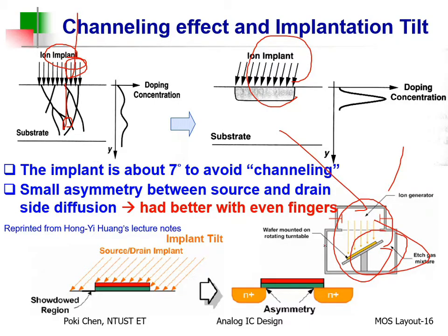But in this way, I told you already, the source, this area and that area, if it goes in this direction, the side diffusion here will be much larger than there. It means what? Your source and drain will never be exactly the same. They are not symmetrical at all. Got it? But for your simulation, it is supposed that source and drain are symmetrical. Right? So how to solve such kind of difference between the layout and your post or presim? You need to do such kind of stack layout.